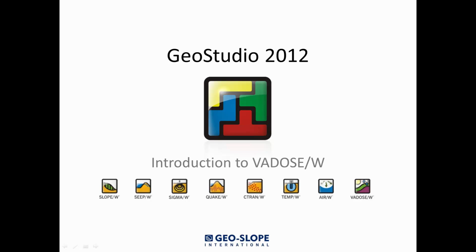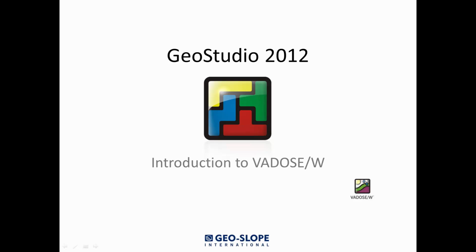This tutorial introduces how to use the Vadose W product of GeoStudio 2012. This tutorial video has been designed to help walk new users through the basics of setting up a Vadose zone analysis in Vadose W. Vadose W is a rigorous finite element program that links the stress state of the moisture in the ground to the demands of the climate and computes how water moves through the soil-atmosphere interface.